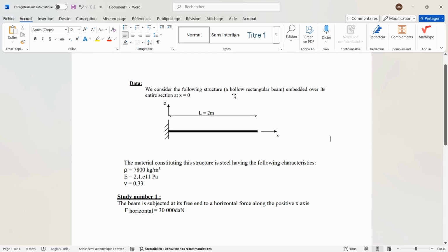So we have this rod, which is only a beam, but we are going to model it as a rod in our software as it's a traction force, right? If it were flexion, we would need some deformation from the flexion, so we would put in a cross section and model a real beam. But as long as it's traction, we can go with the rod.